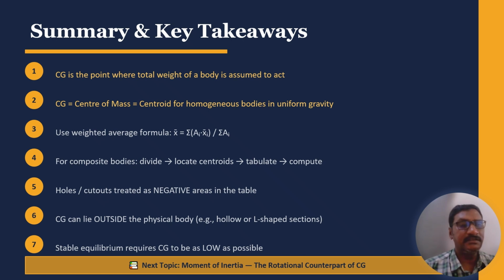And the next takeaway is that the center of gravity can lie outside the body. The center of gravity is not required to lie within the physical material of the body. So for hollow shapes, rings, L sections, U sections and other non-convex shapes, the center of gravity may lie in the empty space. This is not a contradiction. It simply means that the weighted average position of the material falls in a region where no material is present. So always verify your answer by plotting the center of gravity on your diagram.